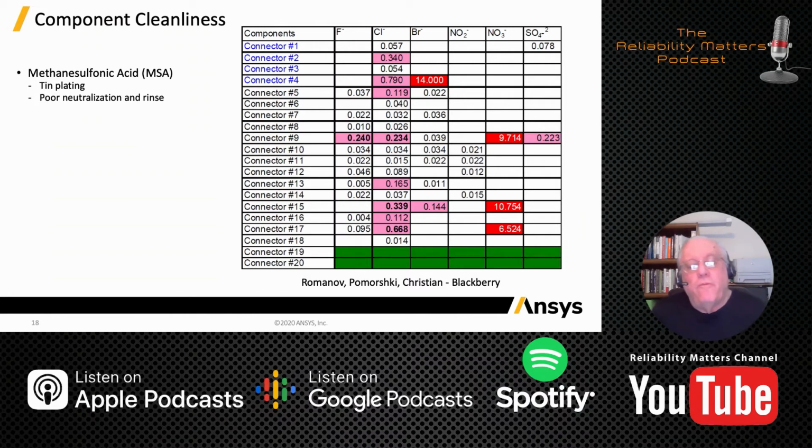And so if your component manufacturer is not doing a good job of cleaning and rinsing, you're going to find that MSA, methane sulfonic acid, as an unfortunate remnant on your components. And we have seen this. This has been reported in more than one paper that's been written about component cleanliness.